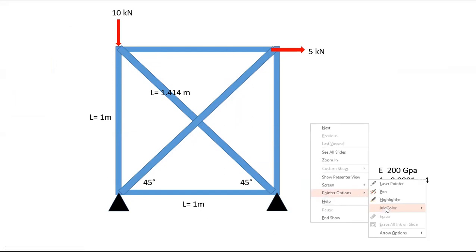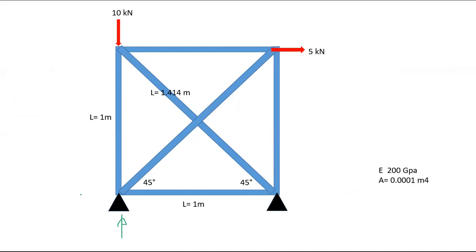So together you have a reaction here, let's say R1, and a reaction here, and a reaction here, right? Always define it on the global x and y direction, right? This node has a force of 10 kilonewtons, 5 kilonewtons, and the other nodes are okay. Length is given. For these members, length varies, right? So it's 1.4 root 2 meters, right? So you have to define.